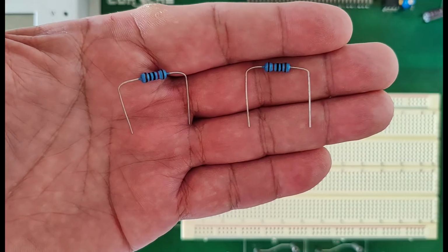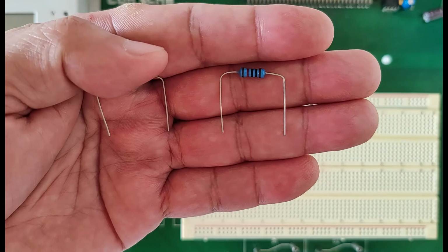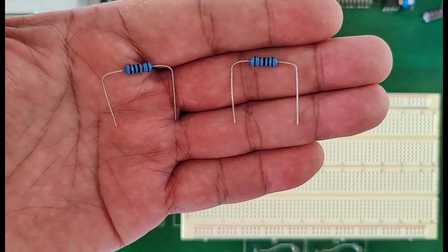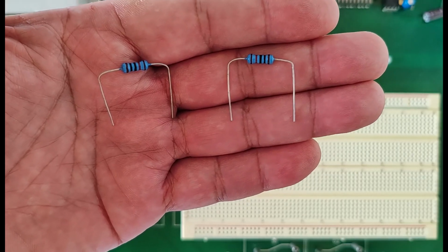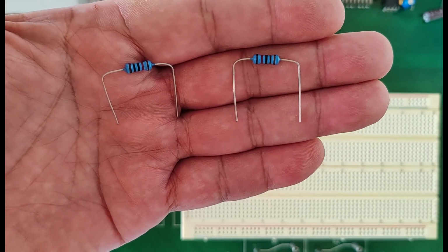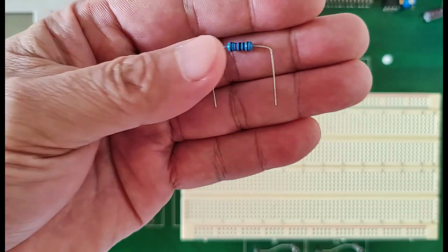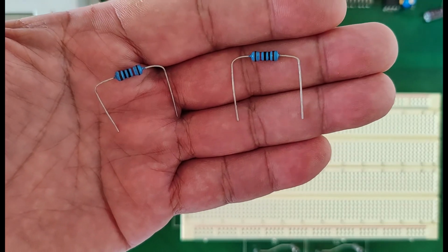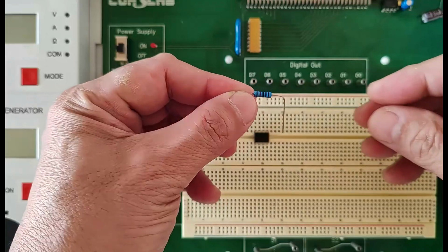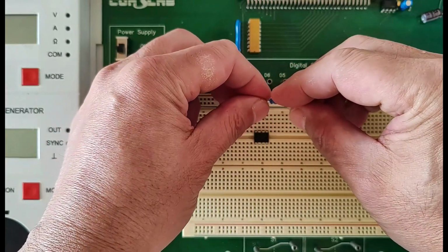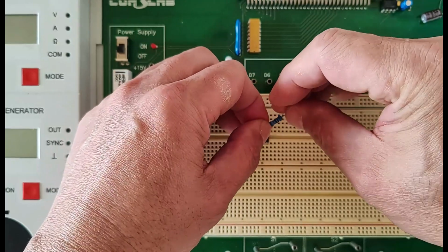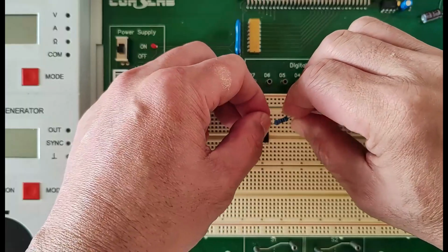Based on the diagram shown earlier, the feedback resistor should be connected to pin 6 in series with the input resistor, and the other leg of the input resistor should be grounded. Now here, there's no problem. I can interchange it. However, if you're given different valued resistors, be careful with the connection. So I could use either one of these as feedback, either one as input. Let's connect it now. The one I'm going to use for the feedback resistor, let's say this one, I'm going to connect to pin number 6, which is somewhere here. Connect it here, pin number 6. I'll connect the other leg somewhere here, like that.